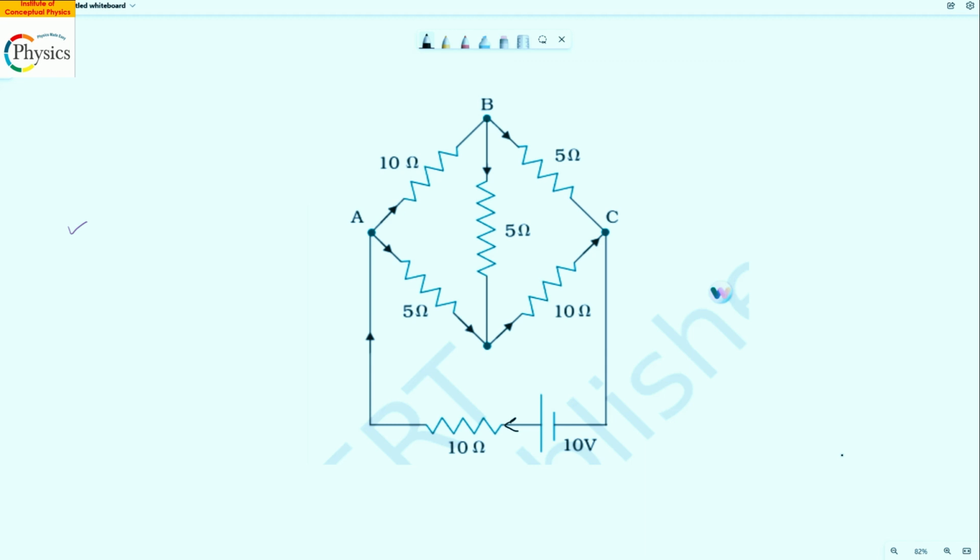The first step, number one, is to start from the battery and always denote the current in the battery as I1. The current enters A, right? So some potential is lost here. The battery has a potential, and some of it is lost across the 10 ohm resistor. The balance potential appears across the balance circuit. So this is what I mean.